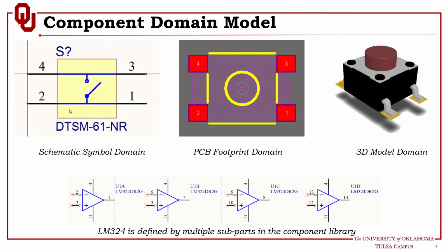The schematic symbol typically includes a shape which can reflect the function of that component and include one or more pins. As we can see in this symbol in here, we have 4 pins representing the function of a switch that connects pin 1 or 2 to pin 3 or 4. In some cases, one schematic symbol can represent the entire physical component.